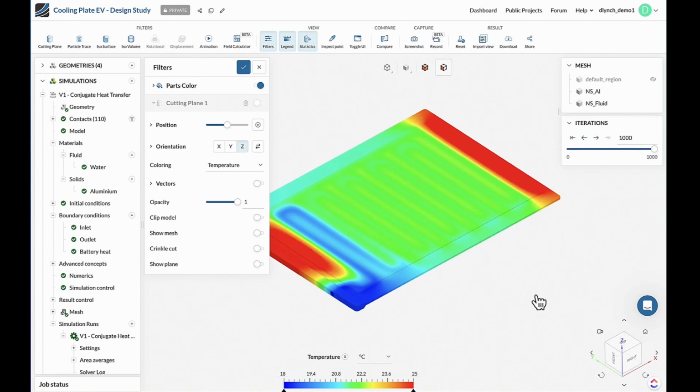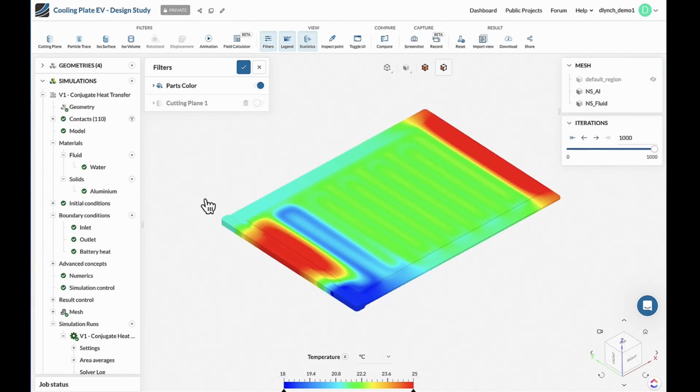We've also got many other administrative features, such as sharing amongst yourselves, your company, with all sorts of different levels of access. But let's talk specifically about this case now. So this is a battery cooling plate. I showed it in the presentation. What we've got here is a cooling channel that goes straight in, coolant in here, coolant out here. And we can see that it cools down this aluminium plate, and there is a power load that's been applied to this that heats this up. And it shows us how well we are actually performing here.